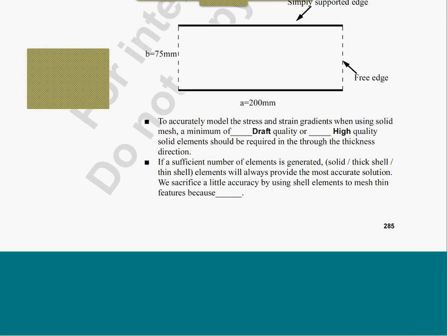Put it simply, if you are thinking of having accurate results across the thickness, then it may not make much sense. We need solid elements only, for any kind of geometry. And from a software perspective, if I remember rightly, there are some limitations. I should say from theory, but something like that, that we may not be able to simulate thermal results or thermal simulation using shell elements accurately. So there are a few limitations that come in that direction.